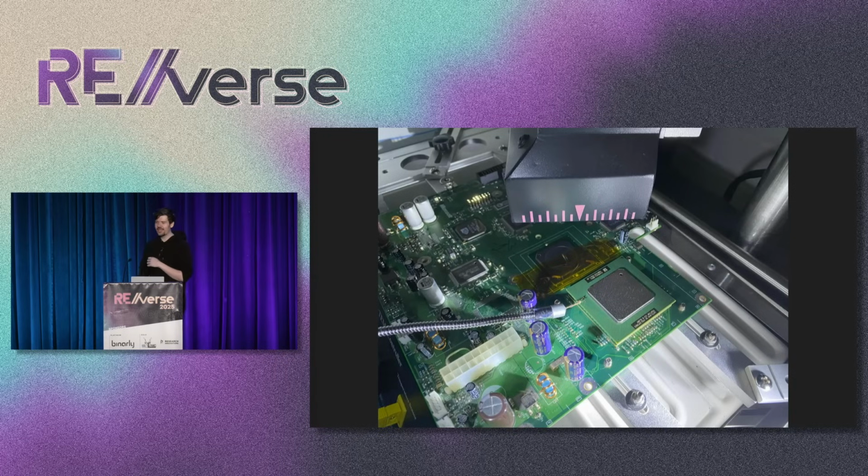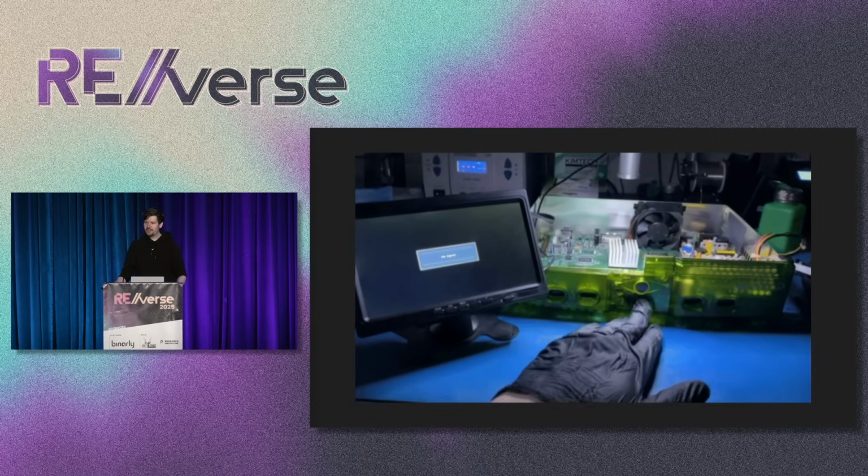There's a few other small things you kind of got to do, not really to the BGA station. This is just me kind of pulling it off. But you have to tweak the voltage, like the V core or whatever, to be lower. But essentially, yeah, it was time to try booting this thing up.